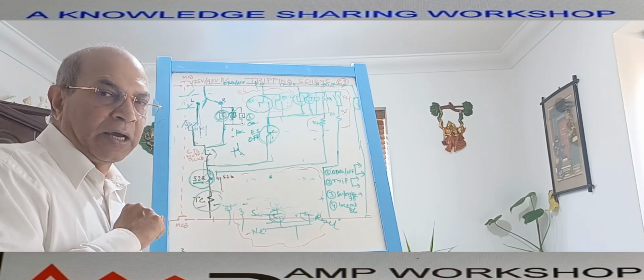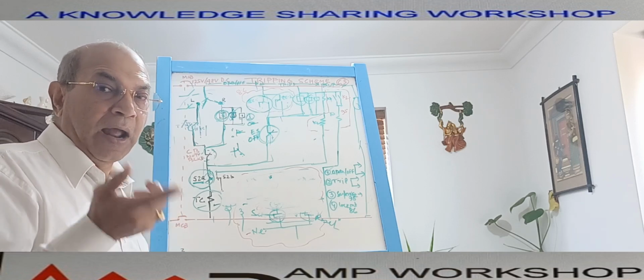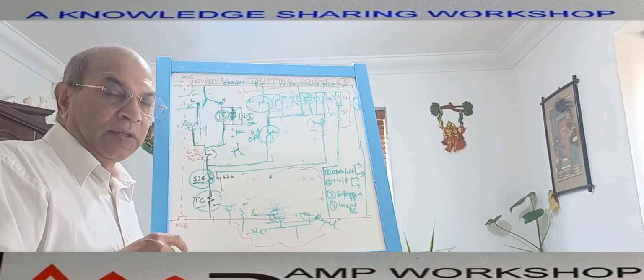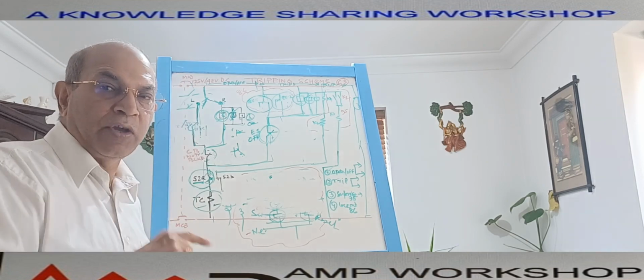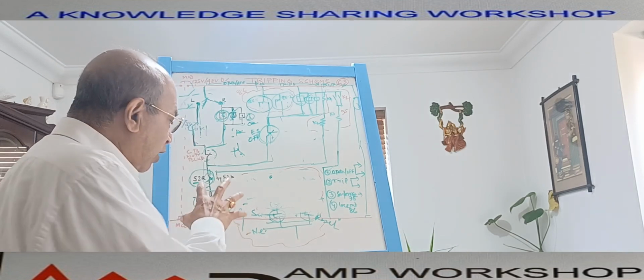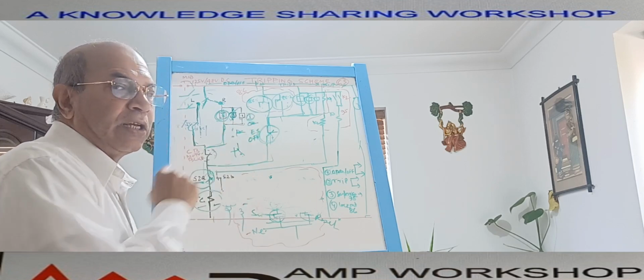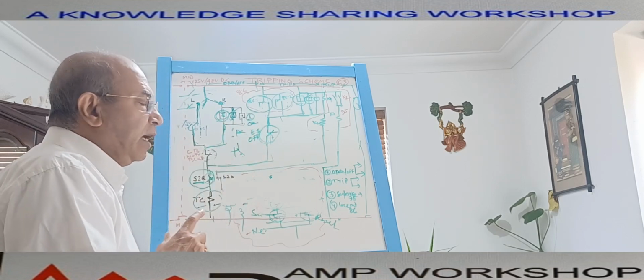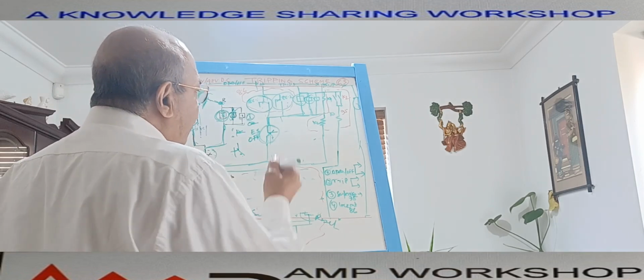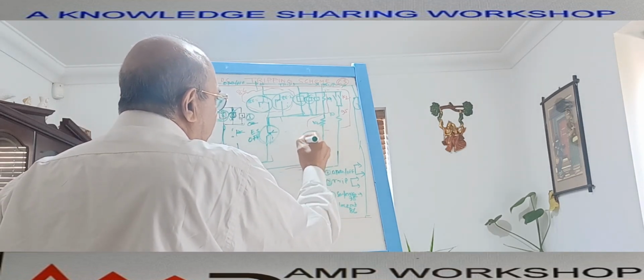If you close the breaker, then the breaker will not trip, and at that time, if there is a fault, then the fault current will be continuously flowing. There is a big danger. So that's why trip coil supervision is required. So we are doing it by a relay. That relay is called the 95 relay. This 95 is a trip coil supervision relay.